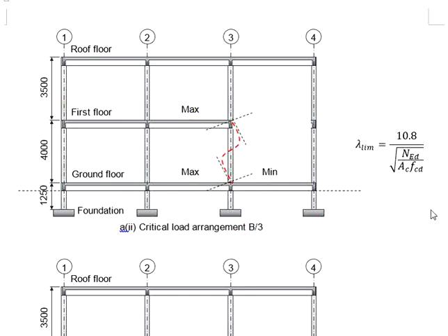Maximum load here will lead to rotation of the joint here. Imagine due to the moment, the horizontal axis of the joint now has been rotated, giving you a slightly inclined joint here. Remember that concrete structures are monolithic at the joint.